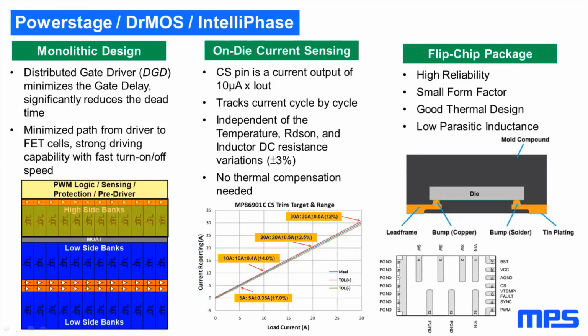Having many drivers for parts of a single MOSFET also allows us to switch off parts of the FET. We call it partial FET off, and it allows us to increase the light load efficiency a lot, as the switching losses are minimized.